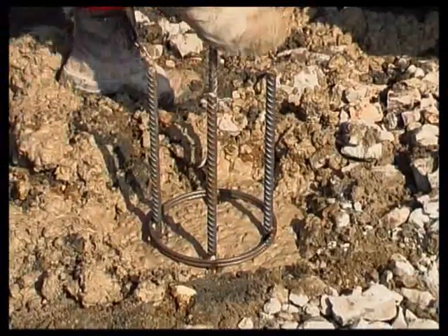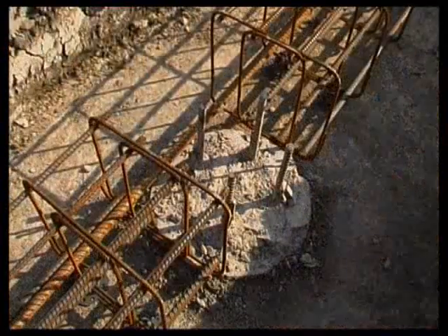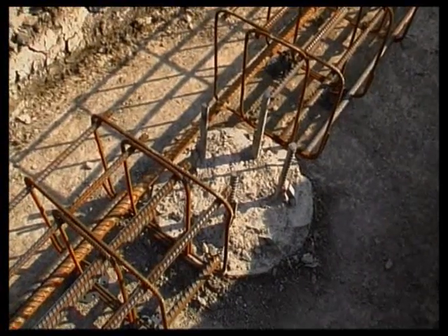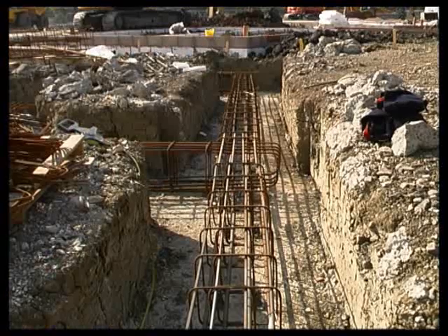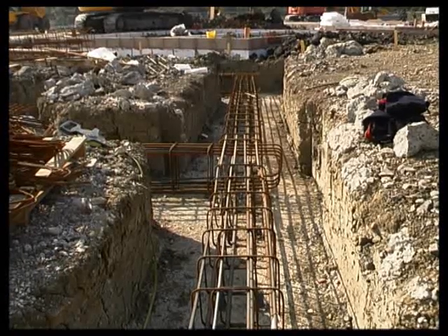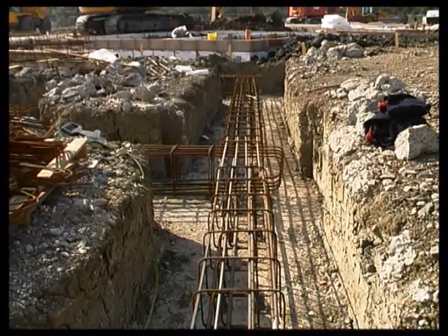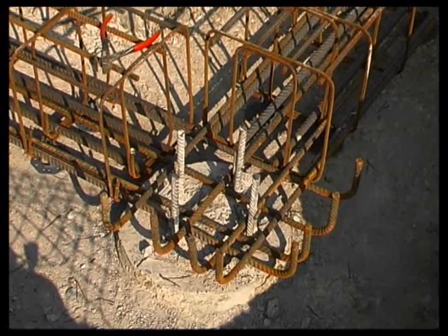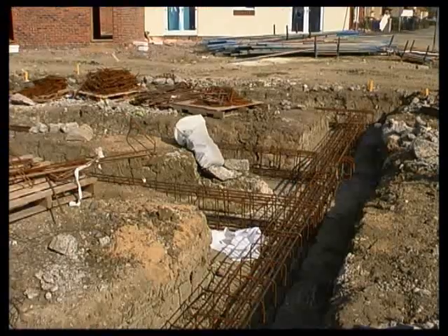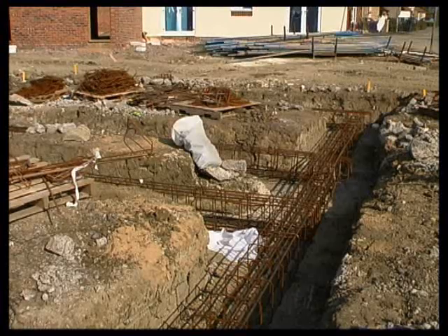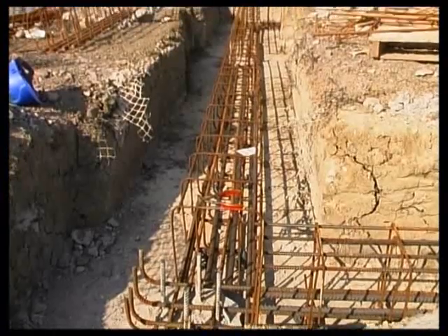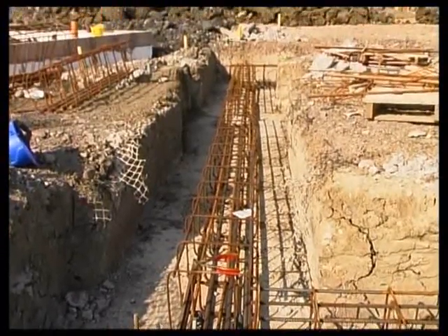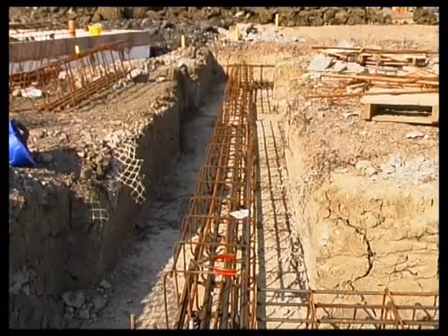The steel projects from the top of the pile and provides a good connection with the steel cage forming the ground beam. The walls of the house are built onto the ground beam, which transfers the loads into the piles. This may look similar to a traditional strip foundation, but the ground beam, despite its name, spans from pile to pile and is not supported by the ground beneath it.